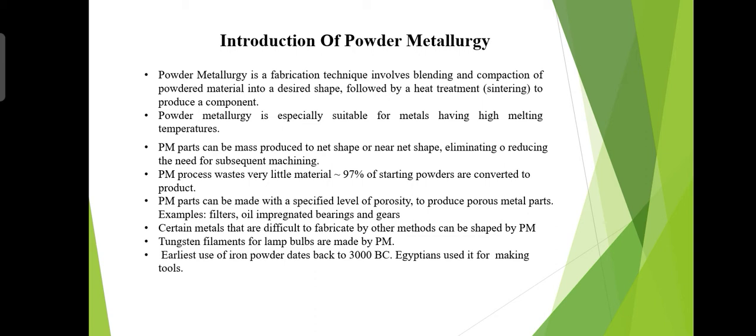Powder processing is also useful for producing small lots of new materials, since existing commercial powders can often be blended together to produce the desired composition, avoiding the cost and facilities required for custom melting. Powder metallurgy is also capable of producing a wide range of product forms, ranging from billets to preforms to near net shape parts.